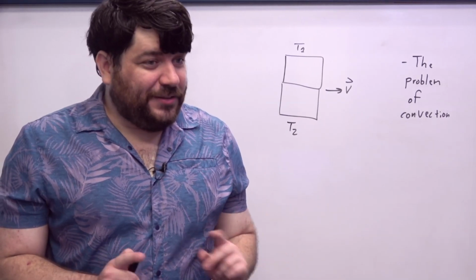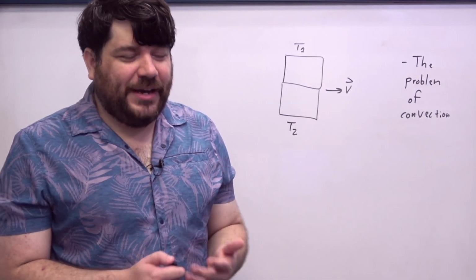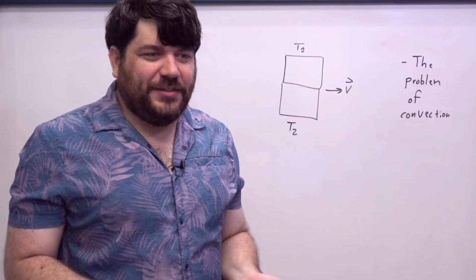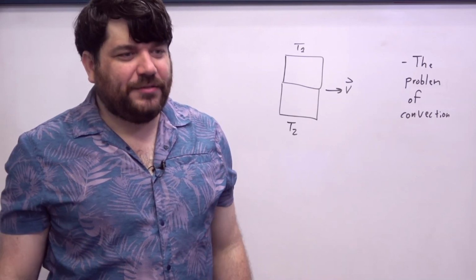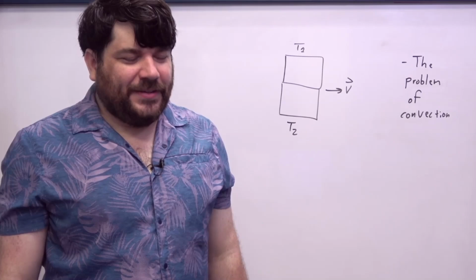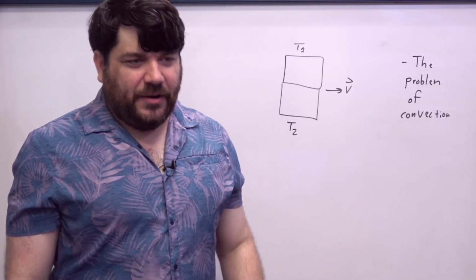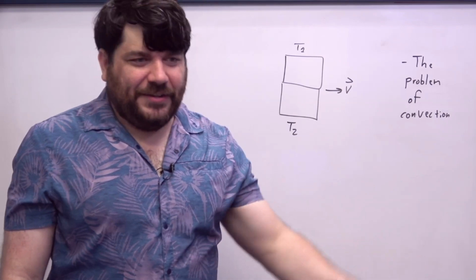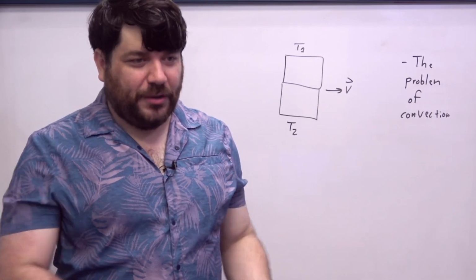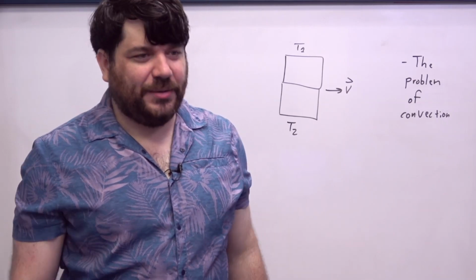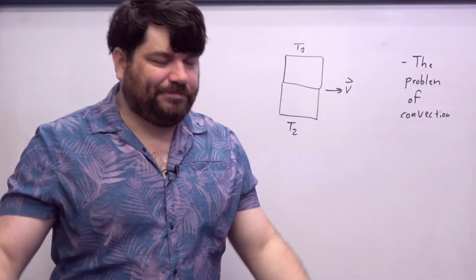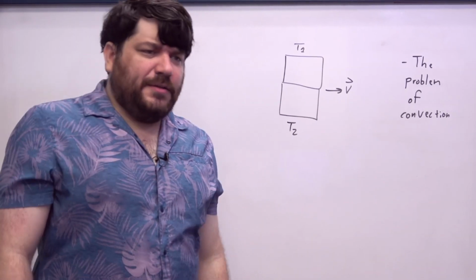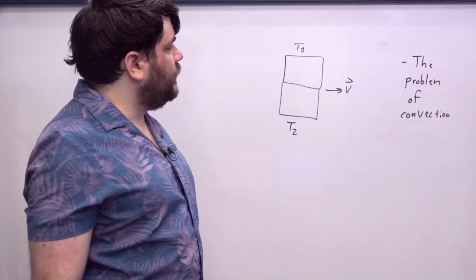And from the perspective, at least, of undergraduate heat transfer, the fact of the matter is that we don't. We basically just resign ourselves to saying, well, we're just going to have to treat them as being semi-infinite. And then the real physical question is trying to figure out what the h is between that semi-infinite fluid and whatever other object we're dealing with, whether it be a solid or another semi-infinite fluid. So, how can we show this issue?